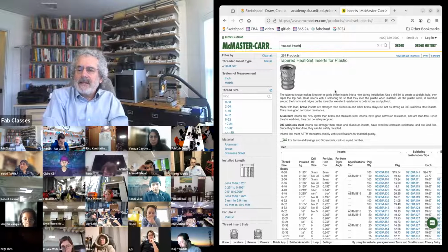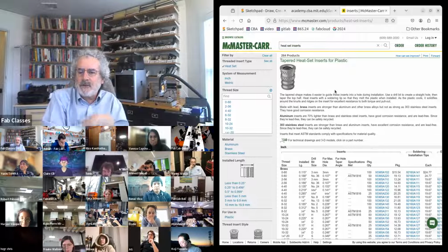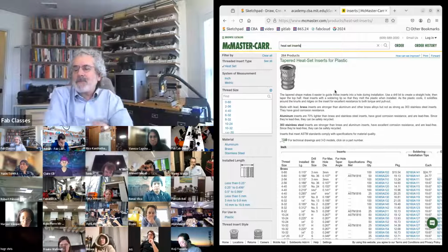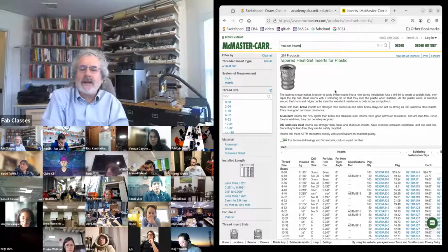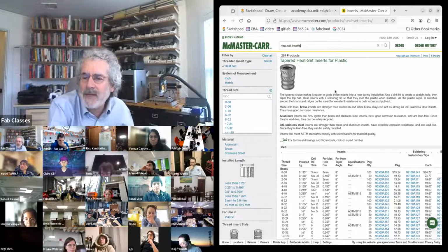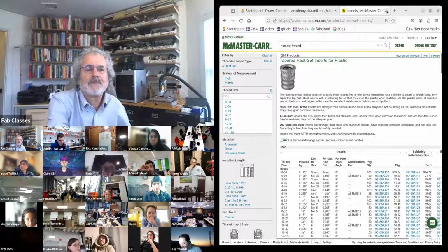Let's see, Leo's asking about Delrin. Delrin isn't a great structural material. It's fairly squishy. It deforms fairly easily. And acrylic isn't great. It cracks. Those aren't happy machine building materials.